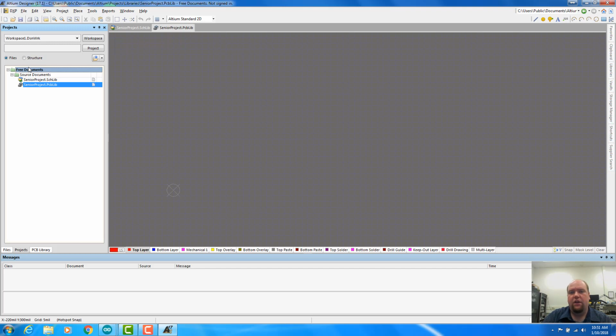So if you are moving a file and it's relying on that library and it's not going to be able to access it outside, make sure it's got some local reference, make sure there's some way that it's a library that you typically use with your parts. So what we're going to do is first start by looking at the PCB footprint. So we're going to define the hardware side of it, the PCB side of it first.